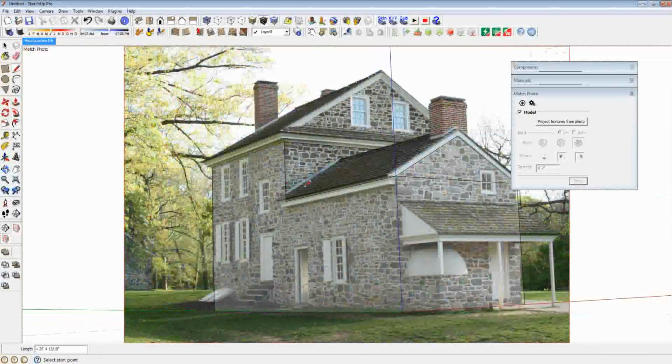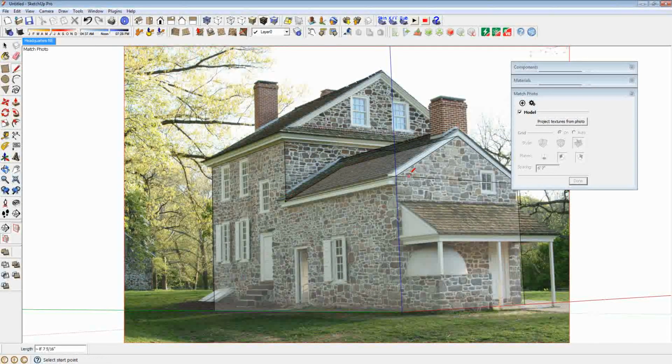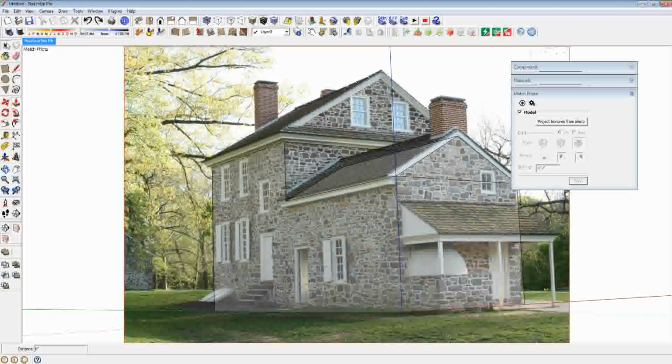For things like the roof, I can close that off because I know based on that portion, if that snaps to there, that'll come down and hit there. And then when I actually set things up for this portion, I'll end up using the PushPull tool, give myself the actual thickness of that roof, and then you can see it starts to line up again. So just a lot of little pieces here and there, putting them all together, and actually figuring out where things go. This portion here that juts out, now that I have this portion on that wall drawn,